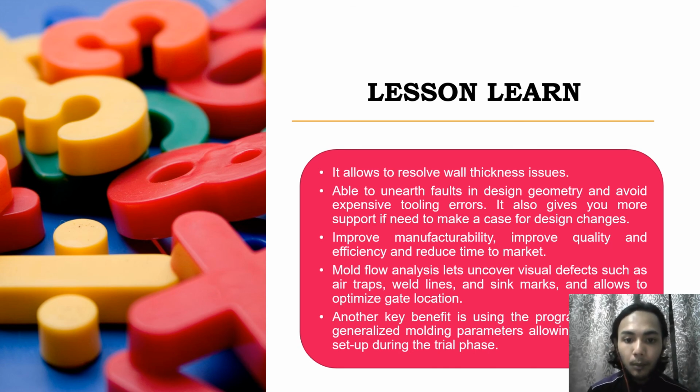Fourth, mold flow analysis lets us uncover visual defects such as air traps, weld lines, and sink marks, and allows us to optimize gate location. The last key benefit is using the program to predict generalized molding parameters, allowing for efficient setup during the trial phase.